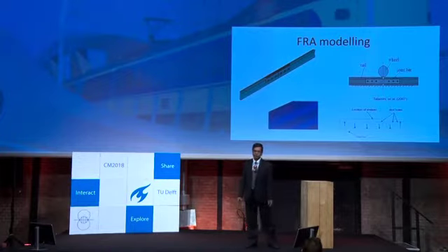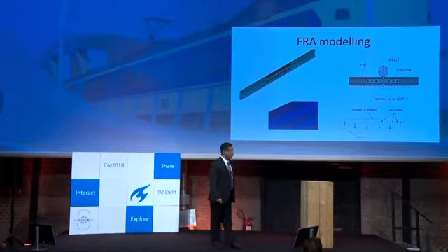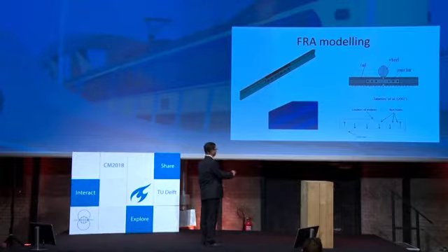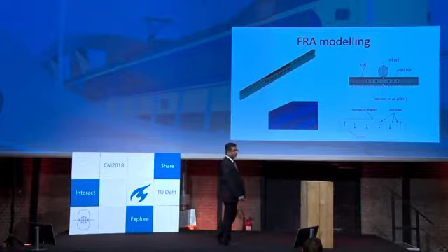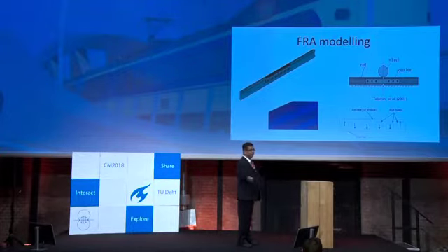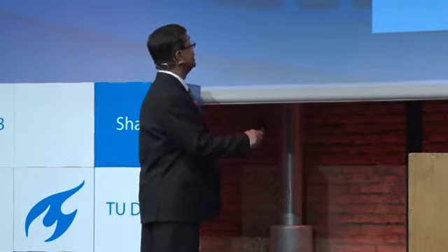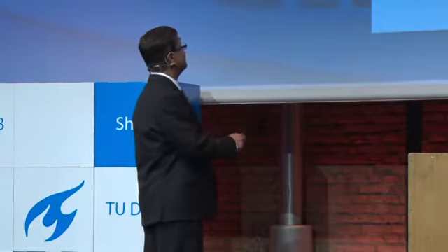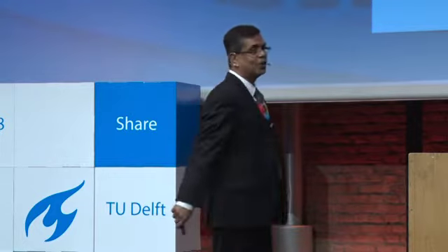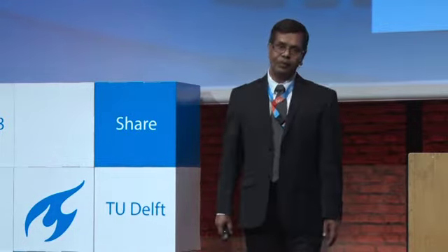So why 12 meters? Because if we put a load here, the 6 degrees of freedom can be nullified, can be 0, far away from the applied load. How far? We calculated that it is 6 meters from there, 6 meters from there. So that's how we got 12 meters long.